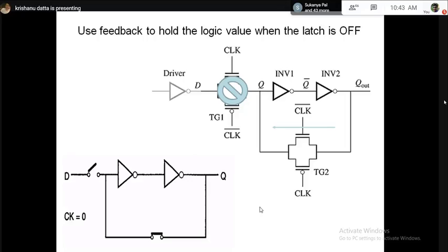Now if you compare to the original latch that I told you, 22 transistor, finally we got an extremely robust latch with 8 transistor. Still it is much more than 50% improvement. This is why transmission gate based latch is so popular in industry.